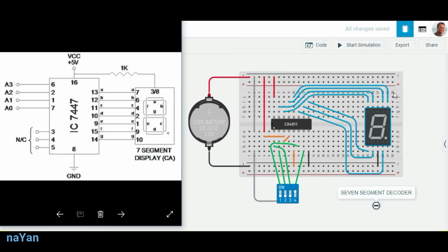When we connect in our actual lab environment, or implement this circuit on the breadboard inside our lab, you can maintain the sequence. We can use this wire first, then this wire, then this wire, and so on. In this way, your circuit will look a little bit clean, so that if we have any error in our circuit, it can be detected easily.